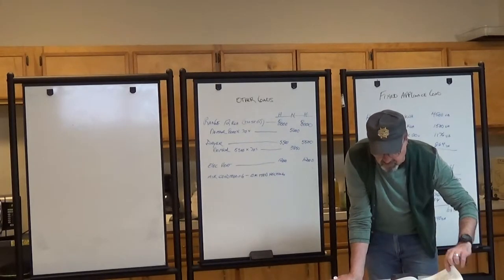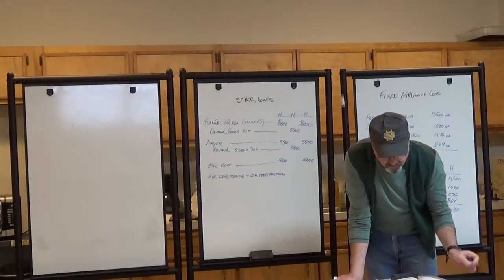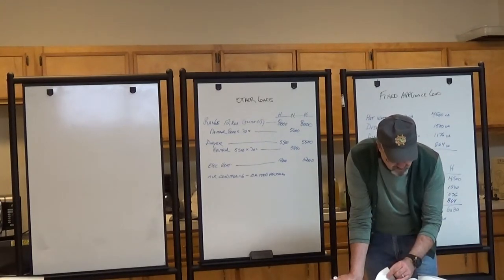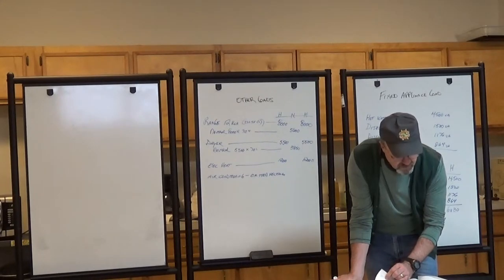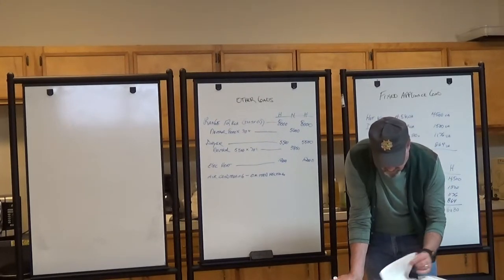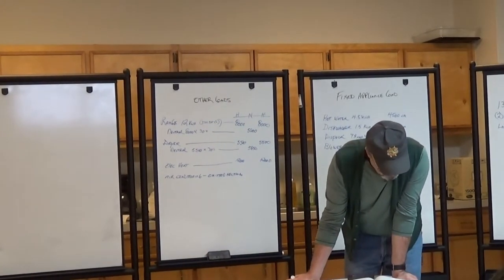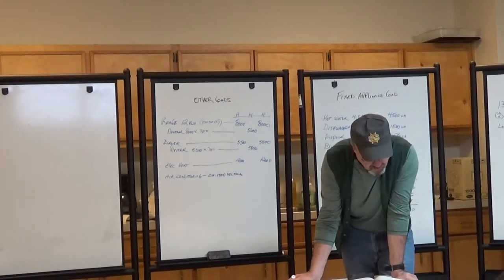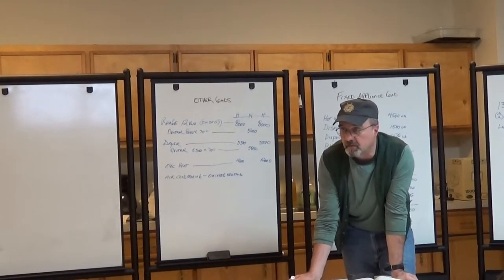That's in the 430s. 430.24. And let's see. It says several motors or a motor and other loads. And so that's what we have. We have a motor and other loads.